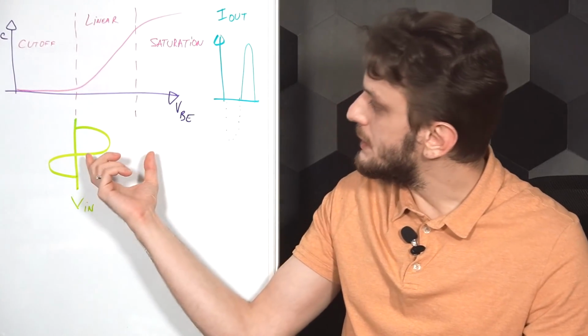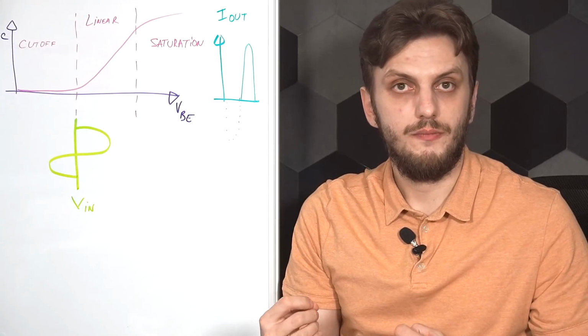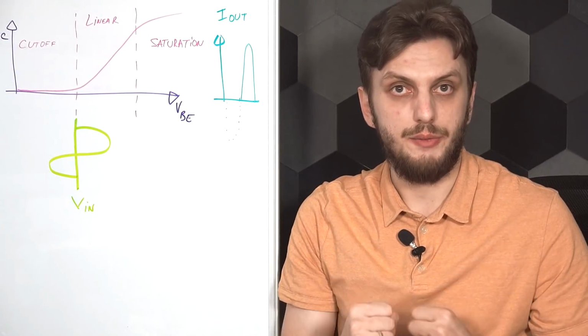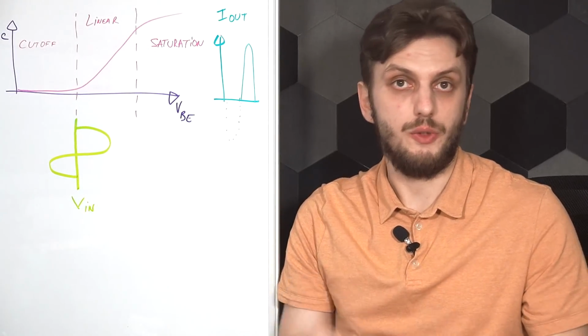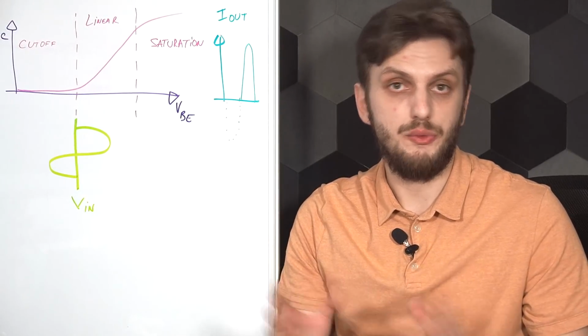So the larger the input signal is, the higher the currents that will pass through the amplifier. So current consumption is strictly related to the signal amplitude. So this sort of amplifier is far more efficient from an energy consumption point of view, especially when non-constant amplitude signals are being amplified.